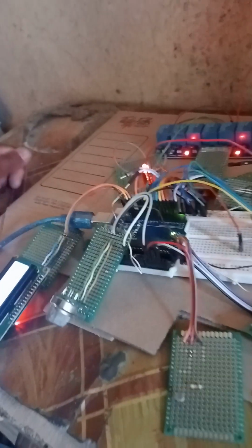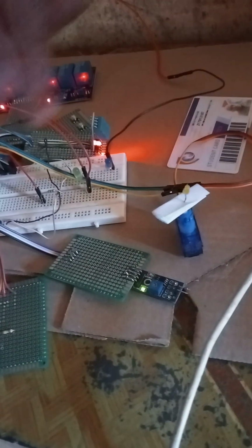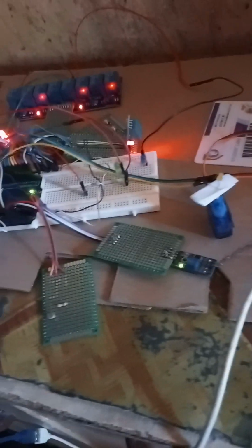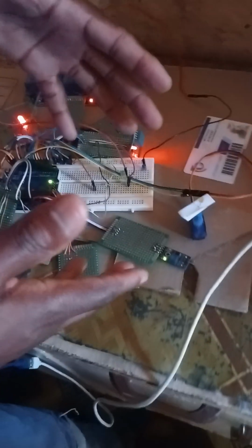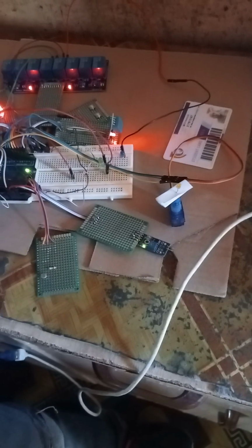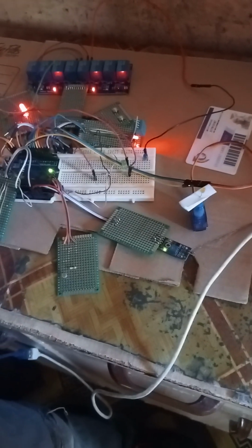Coming here to my serial monitor, as you can see my values here: the moisture of the greenhouse, the temperature, the light intensity, and the values of the smoke inside the greenhouse. Here you go, they're increasing or decreasing. The smoke detector is connected and controls the servo motor. If there's too much CO2 or smoke inside the greenhouse, the servo motor will turn 90 degrees to open up the window so that fresh air can come inside the greenhouse.